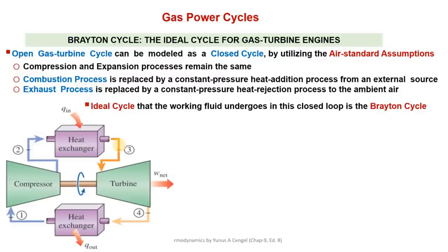Right, so maximum pressures in gas turbines are very low compared to steam turbine inlet pressures, but maximum temperatures in gas turbines are very high compared to steam turbines. So steam turbines have to face very high pressures, while gas turbines have to face very high temperature, not pressure.